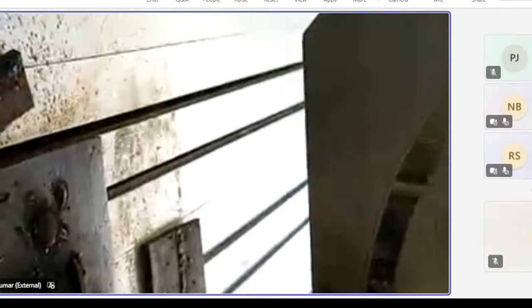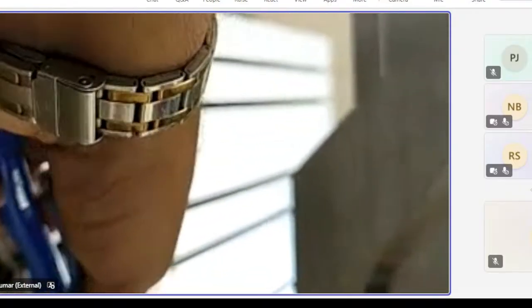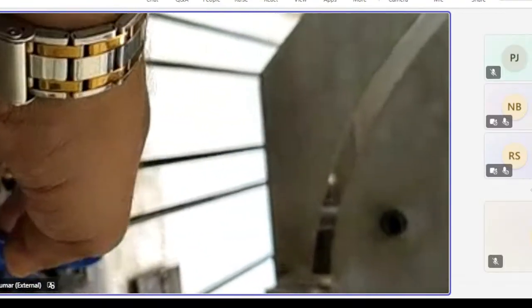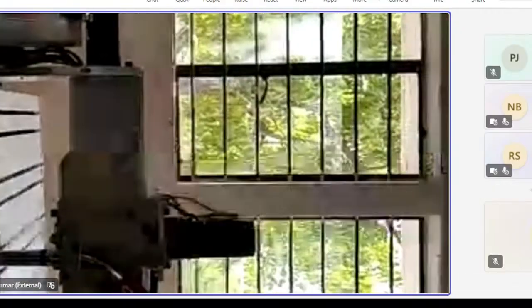And here also one thing can be seen: in this particular bead, a defect is continuously being created, because the single layer is not coming out properly due to accuracy. This kind of defect is known as staircase defect, which you can see over here. Although the bead quality is very good, there is also some defect. This is known as staircase defect. Steps are being formed in the part. So now we will move on to the bidirectional strategy.